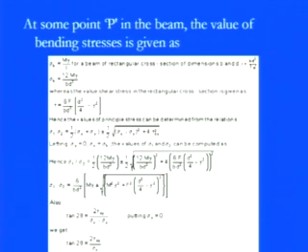So now you see we have the standard one, but as you can see in the previous diagram, we only have the longitudinal stresses in the x direction, so there is no y component. Sigma y will obviously be 0, because we only have the bending or longitudinal stress along the x axis. So sigma x is there, which equals sigma b, which equals 12 M y divided by b d cube.